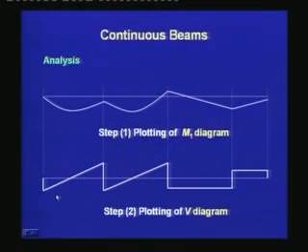From the M1 diagram, we are calculating the V diagram. The V diagram is obtained from the relationship V is equal to dM1 divided by dx. Thus, once we take the differentiation of this curve, we can plot the V diagram, and the V diagram will look something like this, that in the first end span we have the V diagram linearly increasing when the profile is parabolic, then there is a jump at the support, and again in the intermediate span it is linearly increasing.